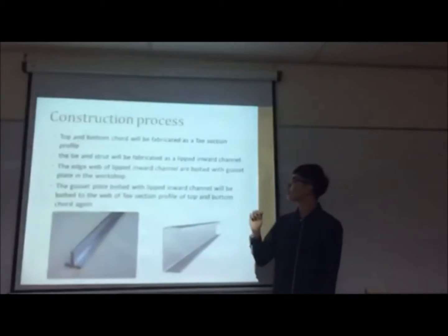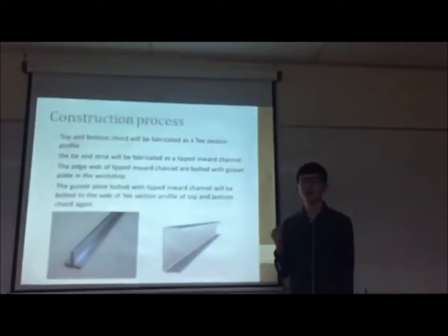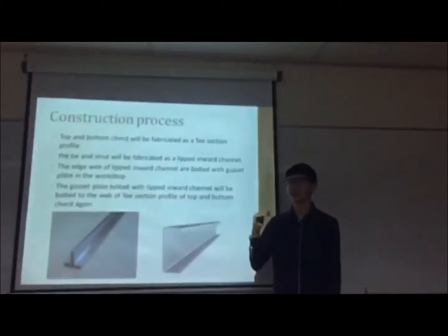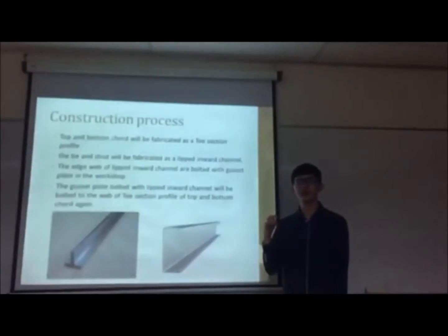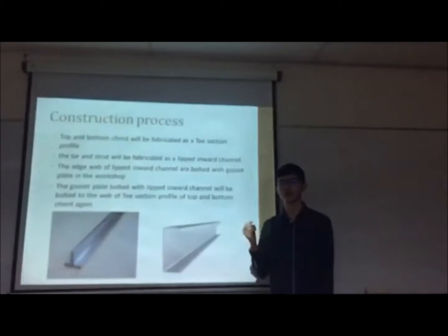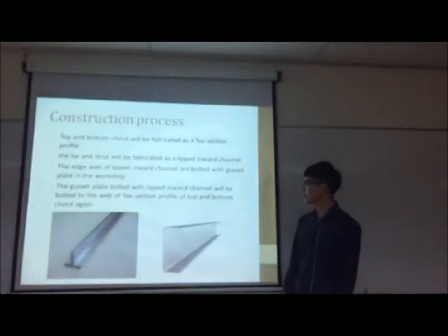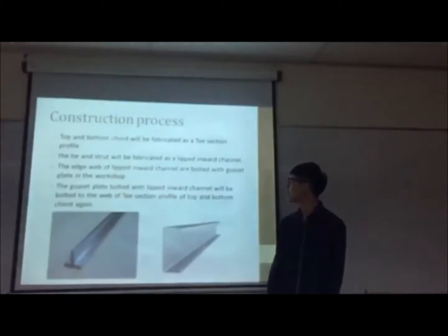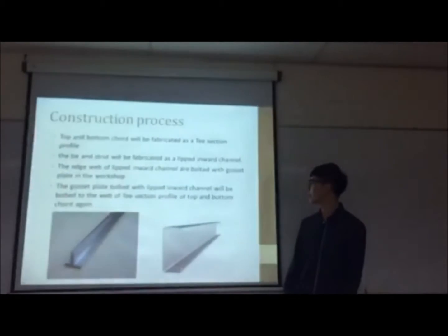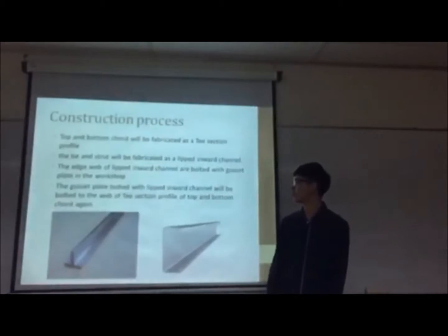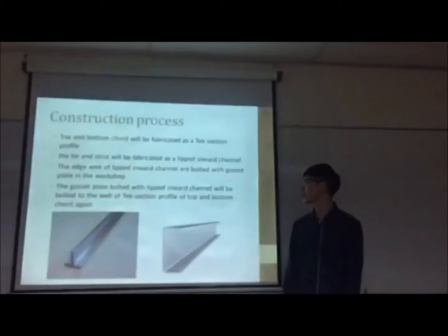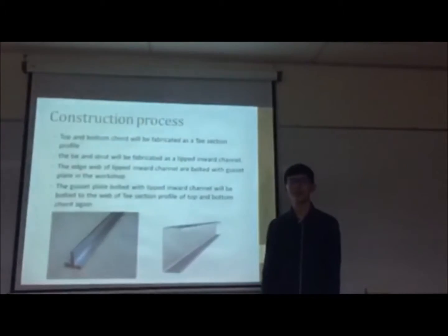The edge web of the lip-inward channel is bolted with the gusset plate in the workshop, so at the time of constructing the truss, the gusset plate bolted with the lip-inward channel profile will be bolted to the web of the T-section profile of the top and bottom chords again.